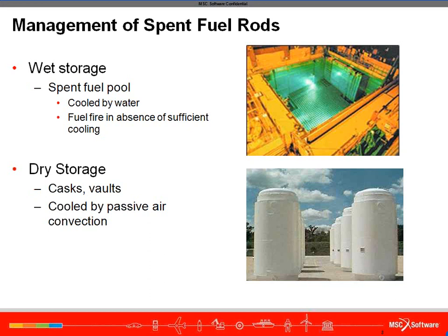The second, the topic of today's discussion, is called dry storage or dry cask storage. Typically, it's used as the operators reach pool capacity for their wet storage facility, so it's a kind of second level. Dry cask storage allows spent fuel that has been cooled in wet storage for at least a year to be surrounded by an inert gas inside a container called a cask.